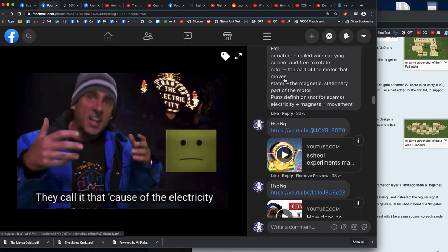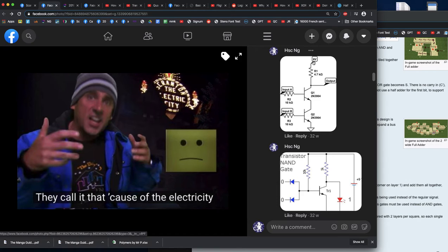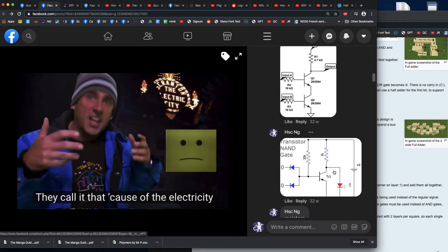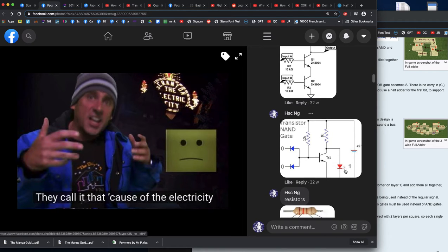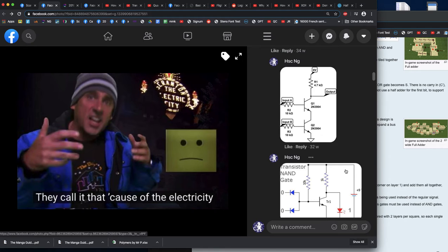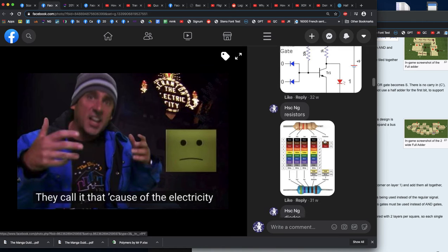One thing I'll quickly mention before we go on is that in this diagram we can see some resistors and some transistors that we identified in the previous video. Resistors can look like this and transistors can look like this. They don't have to have a circle around them to help us spot them. Diodes don't have to have the circle either. We can tell this is an LED because it has two arrows coming out of it. And what's interesting is this is actually the wiring for what's called a NAND gate, which we're going to learn about in a second.